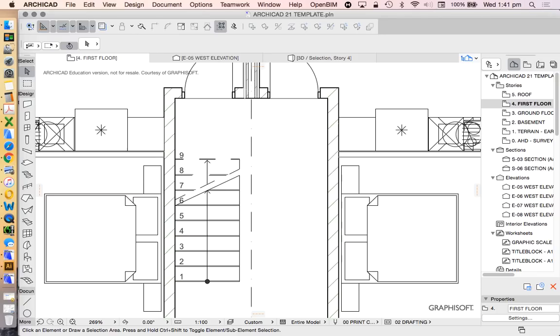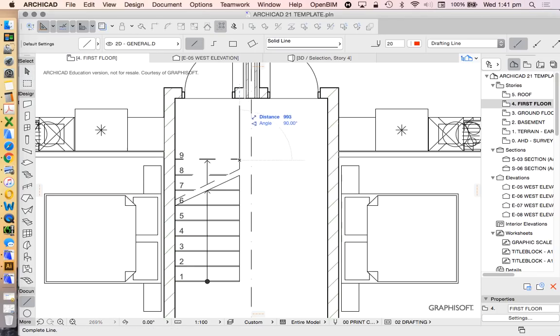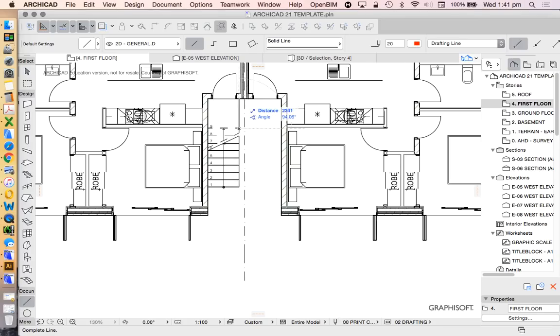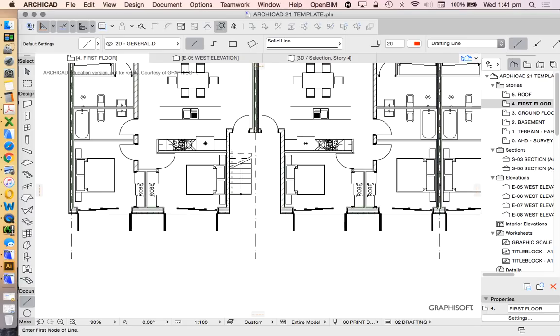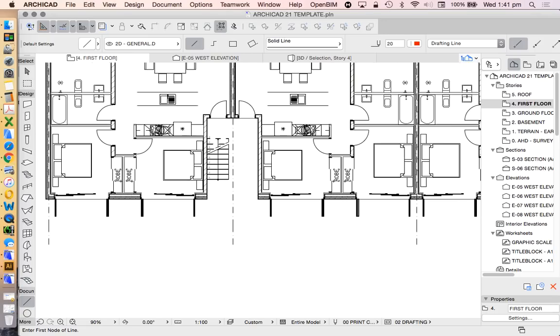So now we've got a distance from the end of the stair to the door or the wall of 1100. That's still definitely within our legal ability, so that's fine. And then we see from here to the end is now 1050. Now I haven't put in a wall here yet. That could of course stick out a little bit if we wanted to, and we might end up doing that. We're going to have a look at that later.